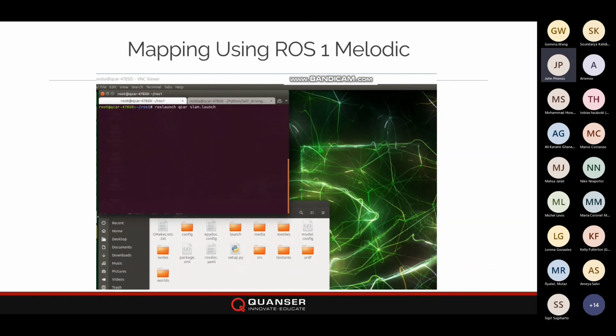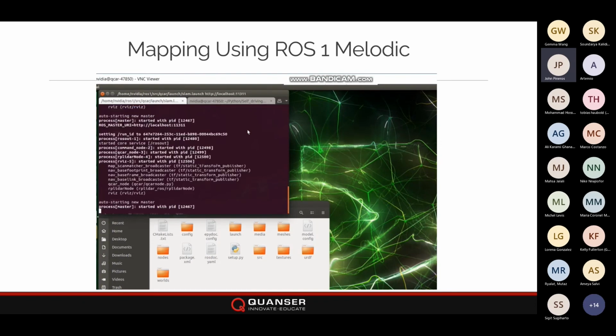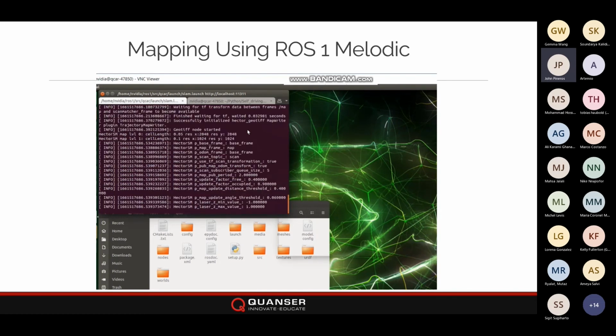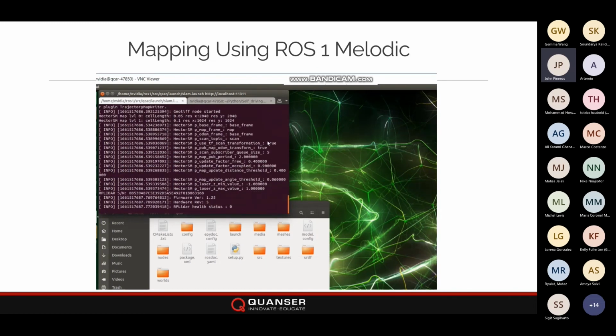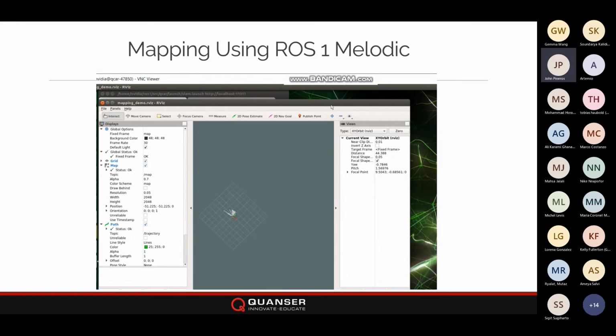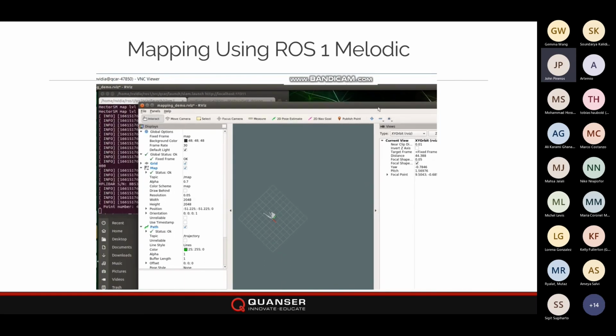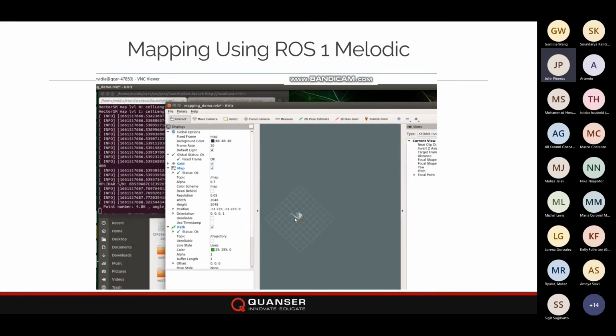Now, going through all of this and finishing what has been already released for the QCar, we can take a look at the mapping example, which is a very interesting one, which takes a look at the LiDAR. We have released a launch file, which already launches RViz and our ROS workspace. And in this configuration here, I'm using VNC Viewer to do a remote connection to the car, and I will be rotating the car in a second, and then you'll be able to see the occupancy grid get populated as the car starts to move around.